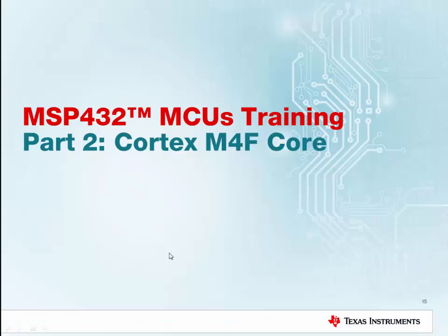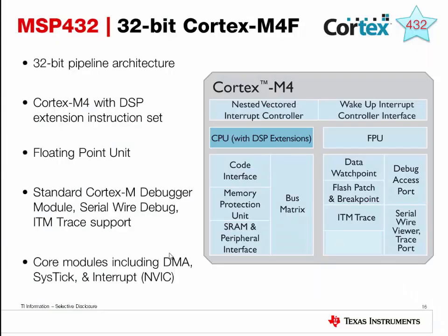Welcome to the MSP432 MCU's training. This is part 2, and we will look into the Cortex-M4F core. The MSP432 uses a 32-bit Cortex-M4F CPU. The CPU has a 32-bit data path, 32-bit register bank, and 32-bit memory interfaces.